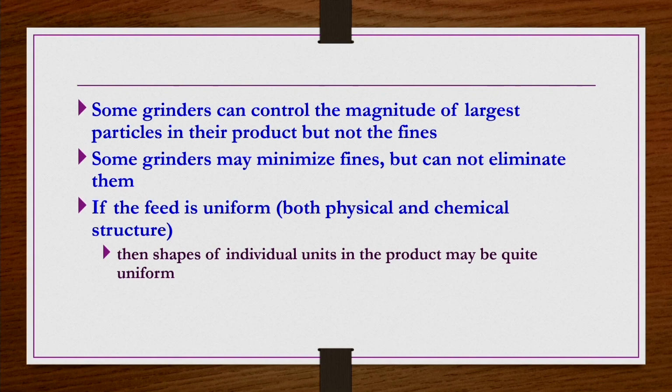Let us say the microstructure of the particles in general has a role in size reduction. When you take a material and do the size reduction, the shape of the particles that you get primarily has some resemblance to their microstructure. Let us say galena: if you take big lumps of galena and do the size reduction, you primarily get particles of cubical shape, not exactly cubical, but resembling a cubical shape. That is because of the microstructure of the galena.